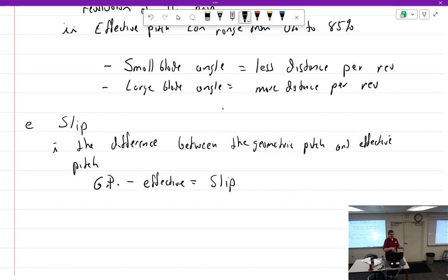Take your feet off the brakes and start to roll down the runway. What's the tachometer going to start doing? Going up. Why did it start climbing? Because the angle of attack changes. The prop becomes more efficient.